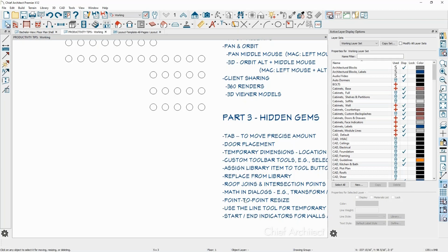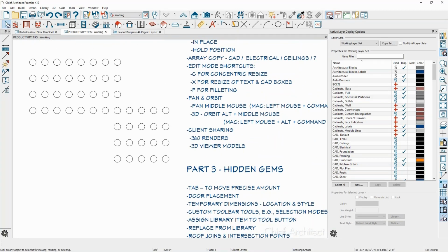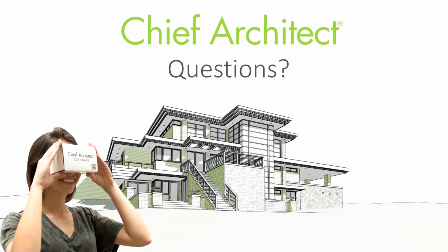So click on the object, click on the multiple copy tool, move your cursor over it, and then you're already in that mode. Ah, okay. That's what I was missing. I was thinking you still had to open it up. Once you've put the interval in, you don't ever have to touch it again, unless you want to change it. Exactly. If you want to change it to another number, then you'll want to open it. Great. That's very helpful. Thank you. You bet.